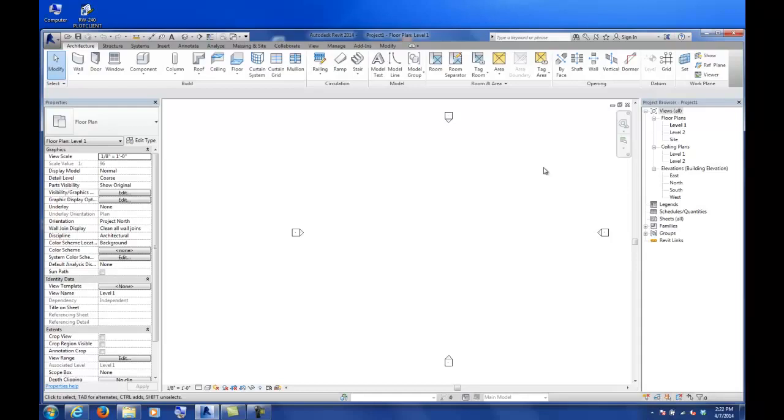Your building probably has a level 1 set to 0, right? You probably have your floors going up from the 0 plane. This site model, when we bring it in, is going to be up at 734 or 735 feet, wherever those contours are. So you're going to have topography floating above your model, and you're going to have to figure out how to merge them together.